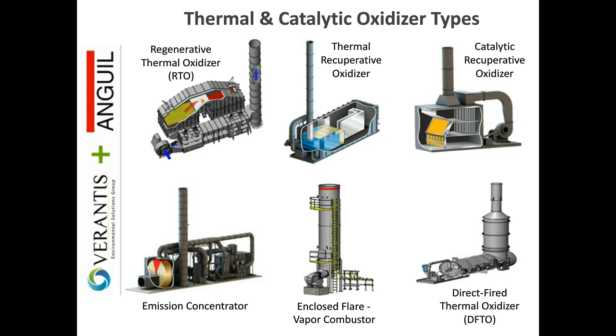The next one over, the catalytic recuperative oxidizer. This is the one that differs a little bit from the thermal oxidizers in that the oxidation process, the actual chemical reaction, is the same. We just use a catalyst to lower the temperature, whereas in thermal oxidizers, we're dependent just on the temperature alone to achieve the oxidation process.